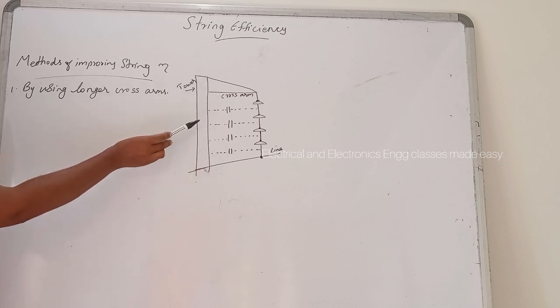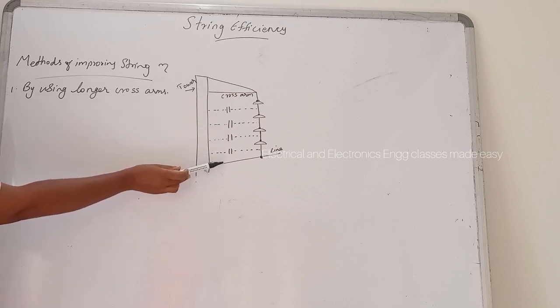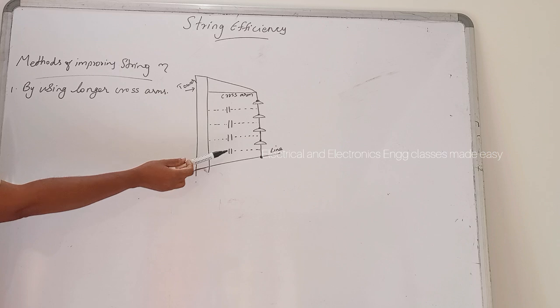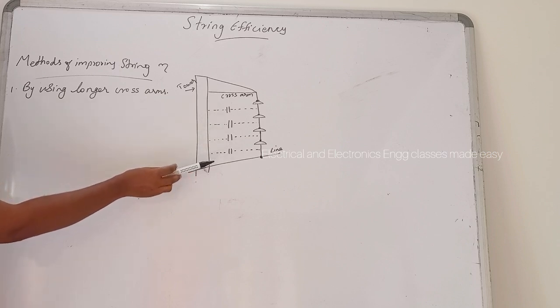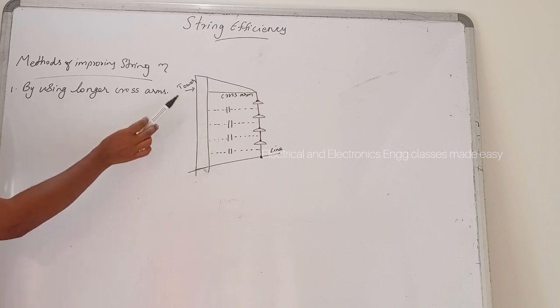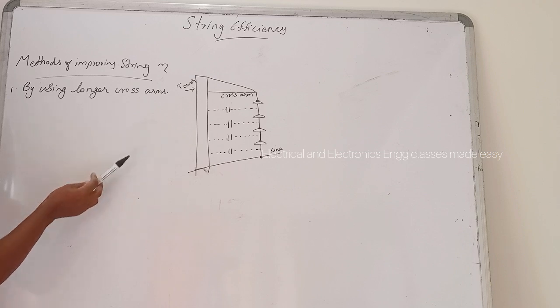If the insulation of the highest stressed insulator, nearest to the conductor, breaks down or flashover takes place, then the breakdown of other units will take place in succession, and this necessitates equalizing the potential across the various units of the string, that is, improving the string efficiency.